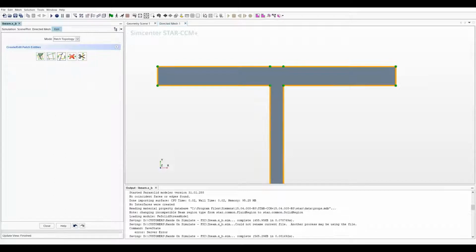So we are going to start from the outer end. Sorry, it's not the inner end. Let's start from the outer end. Click escape if you want to deselect, and we are going to select again. Start from the outer end, the bottom point, the right point, and the top point. Now you can see that we have created a closed entity for the patch curve.